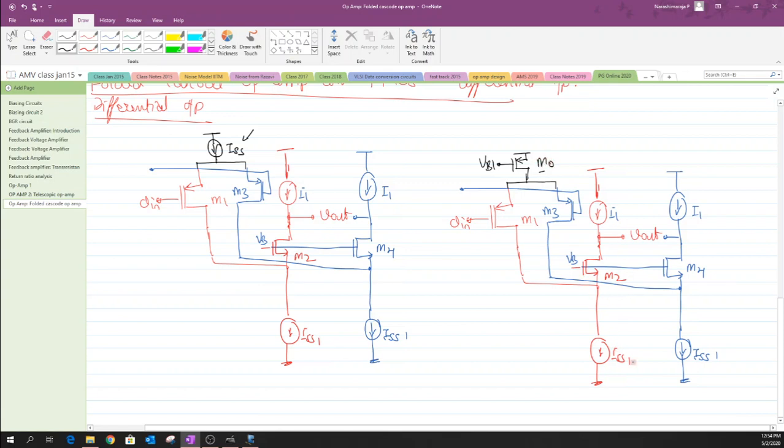And again, now to replace this ISS once more with an NMOS structure. Okay, so these current sources can be replaced with single NMOS transistors that have again been biased as a kind of current sources with some potential like VB2, and let us label these as M3, M4, M5 and M6 here.